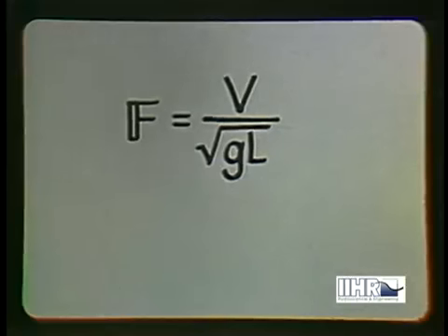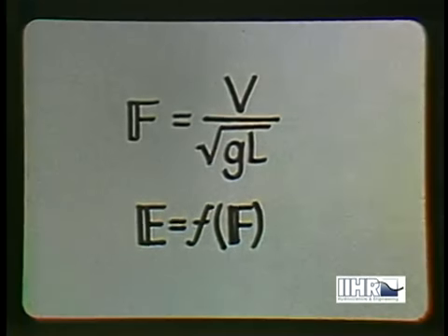If gravity is also involved, an additional ratio, called the Froude number, would exist. The Euler numbers, which would then depend on the Froude numbers, could be the same only if they too were the same. Evidently, if two geometrically similar flows were to be dynamically similar, the velocities would have to vary directly with the square root of the lengths.